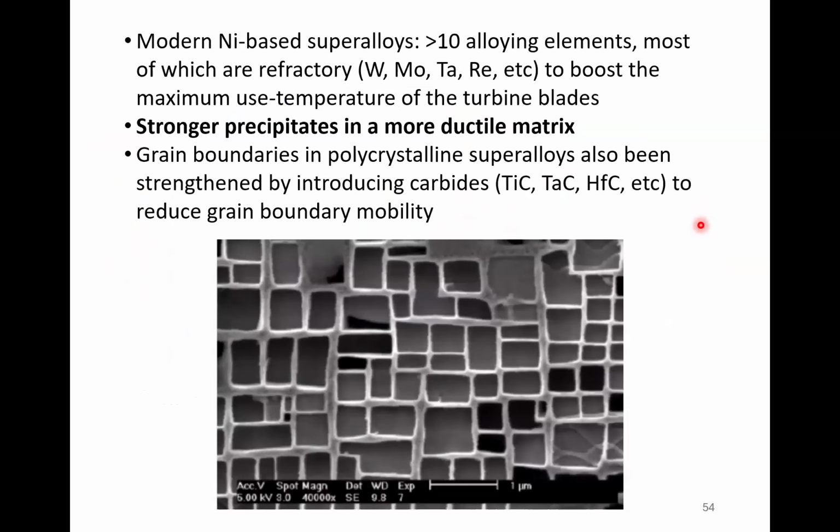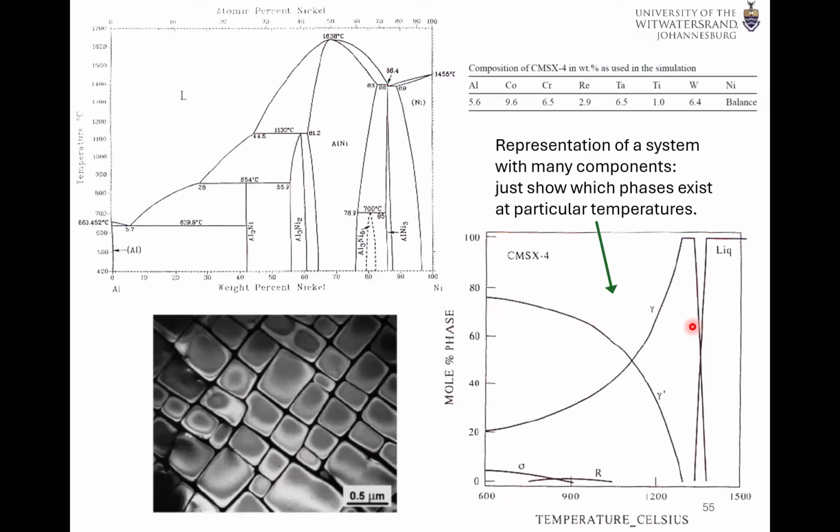So that's really good as well. So modern nickel-based superalloys, you've got precipitate in there, which is harder and stronger, and then you've got the nickel-based solid solution, which is softer, and you can have some carbides, and that gives you really good properties. But what's happening is you're constrained by these temperatures up there. Maybe you can get them to go higher.